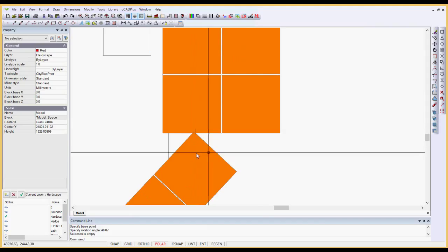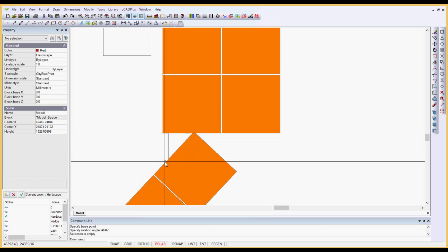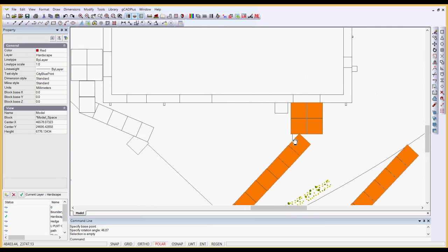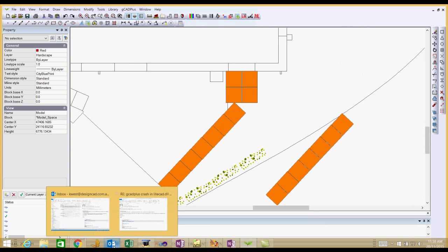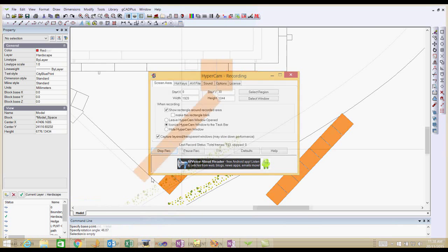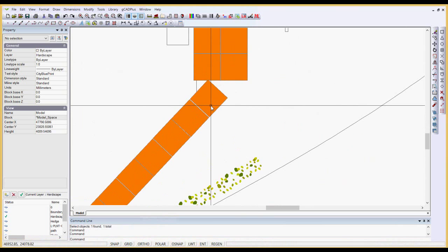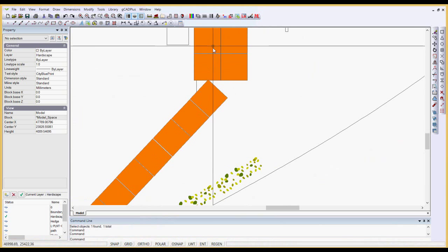You can see here also that maintaining an even gap of 10mm all the way along there, one of the last pavers is going to eat into here, and we need to do some cutting of a block there to fit in. So there's going to be some tricky cutting in that area. So once again, CAD proves invaluable because you are modelling the real world. You can see what's going to happen. The path that we've just placed leaves us with some awkward arrangements towards the end before we move to the porch for the house.